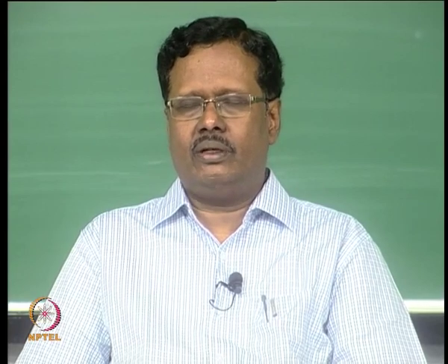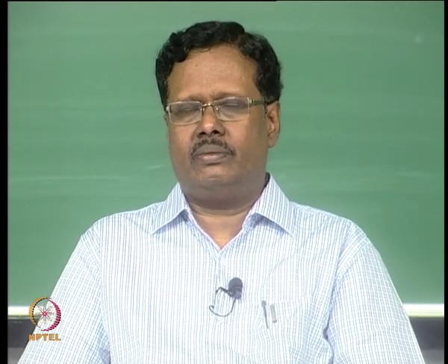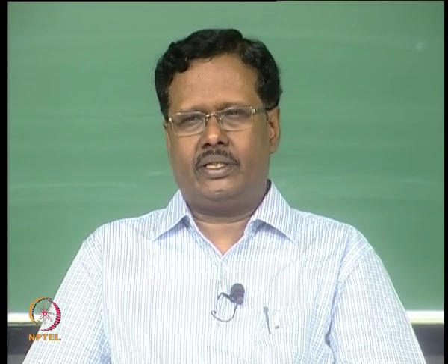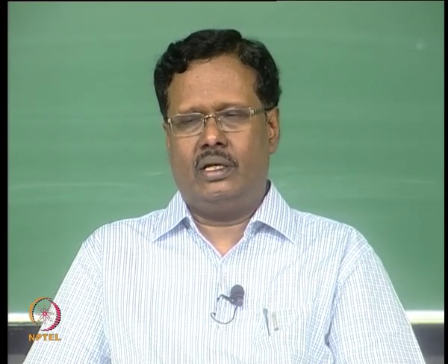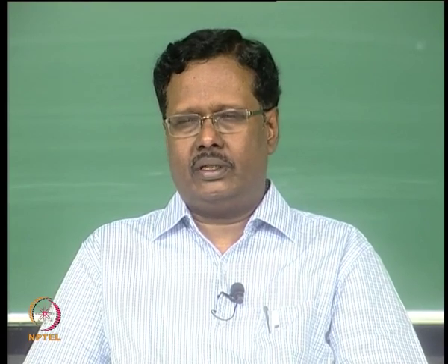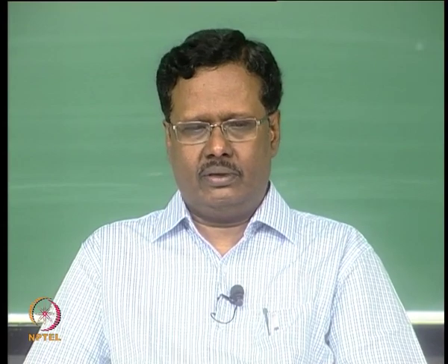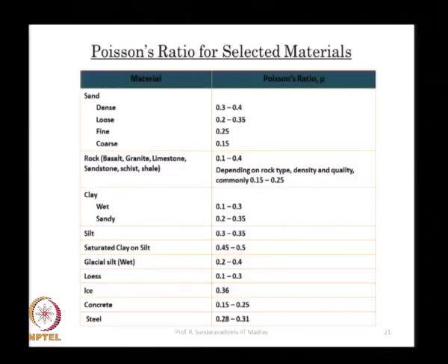Another thing is when you do some analysis, we estimate the spring constant, that is the reaction by the soil. Passive force we cannot estimate, we have to find out the reaction, for which we idealize that by a spring element. For calculating that also we need the Poisson's ratio. Generally Poisson's ratio is less than 0.3 for soil,